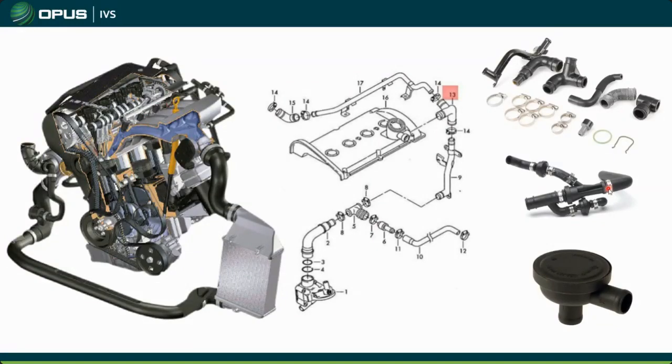And that's mainly because oil has additives in it, and oil itself is just sort of corrosive to rubber and plastic. Now, obviously, they use rubber and plastic that's meant to be in contact with oil, but that stuff is really only going to last so long. And as these things age, you'll start to see these hoses and pipes and check valves all start really gumming up and having trouble. And I would say one of the most common things on these 1.8s, whether it's transverse or inline mounted, is this little elbow hose coming off here to this T-fitting, and then this check valve.